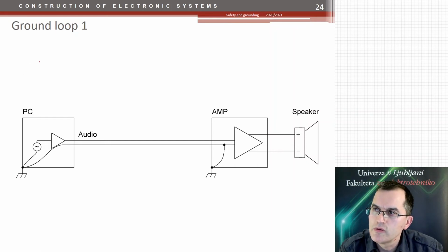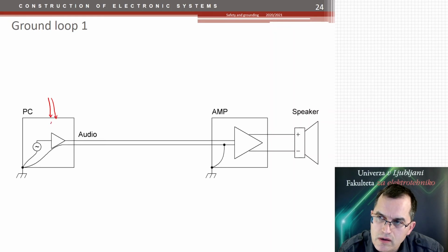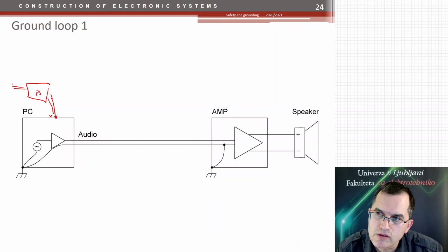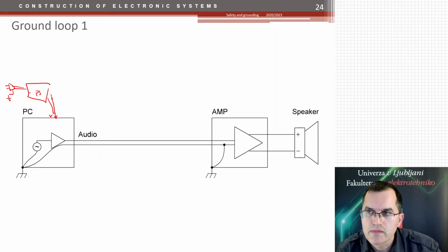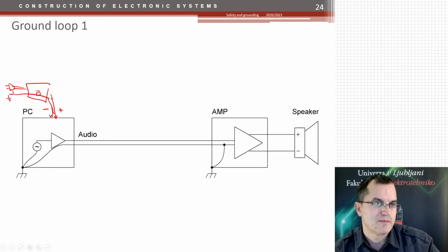So even though your laptop has a 2-wire connection for the power supply, this goes to a power supply, and this power supply is then connected to your socket with a 3-terminal connection. So it is grounded, and the ground is then connected to the minus terminal of your output. So your PC is actually grounded to the Earth through the power supply.